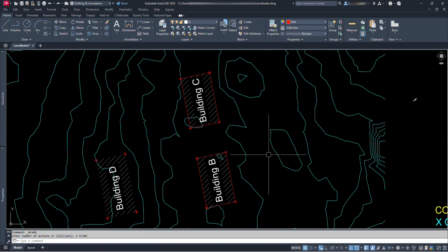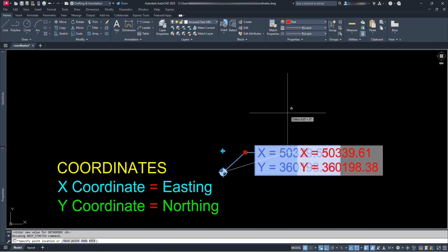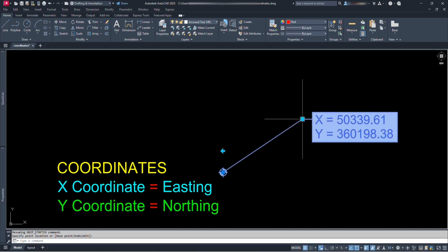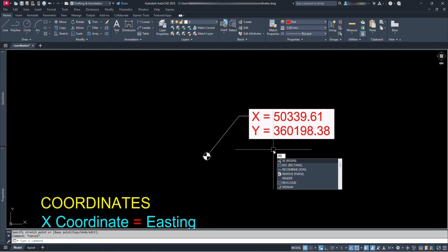And I have prepared one very useful coordinate displaying block. You can simply click at the link provided below for download. This dynamic block, we can flip, stretch and move anywhere and get the coordinates automatically. After moving or copying, we just need to regenerate the drawing by our E command.